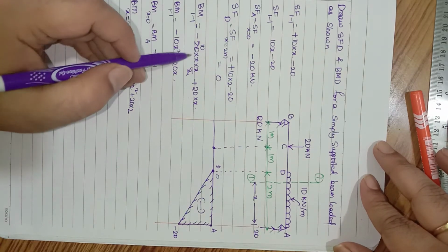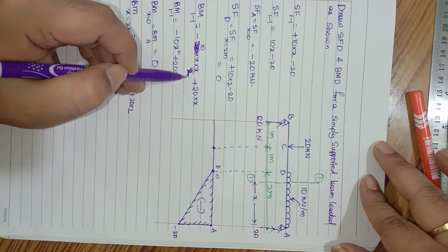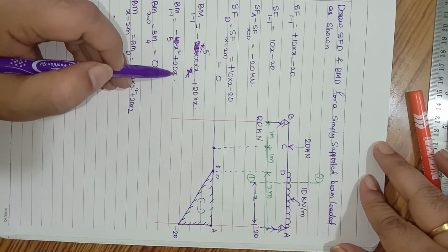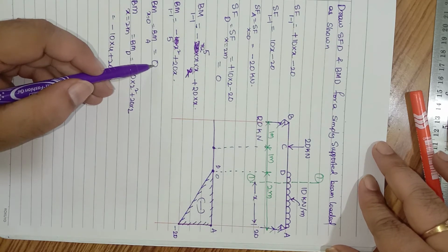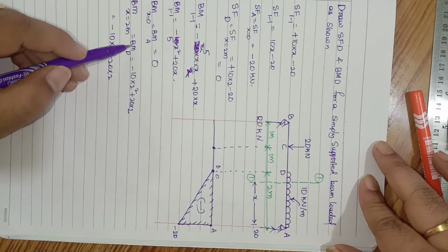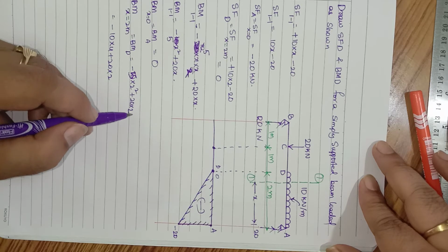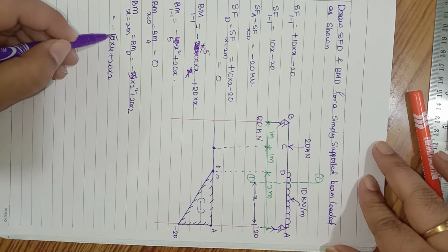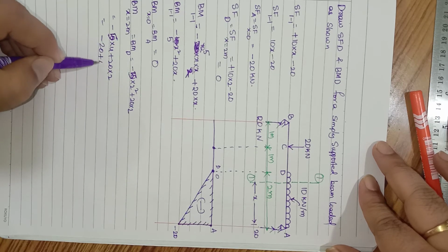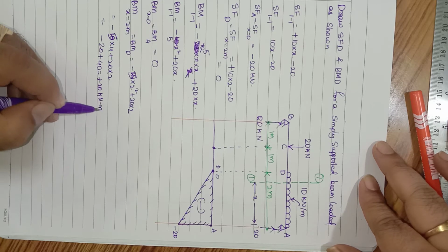so there is a small correction here. Actually this is 10, not 20. 10 into x divided by 2. So this will be 5x square divided by 2. So this is 5x square plus 20 times x. So bending moment at point A is 0, as we have substituted x equal to 0. Bending moment at point 2 meters, right? Bending moment at point D will be equal to 5 times x square plus 20 times 2. So this will be equal to 5 times 4 plus 20 multiplied by 2. This is minus 20 plus 40. It is equal to plus 20 kilonewton meter.